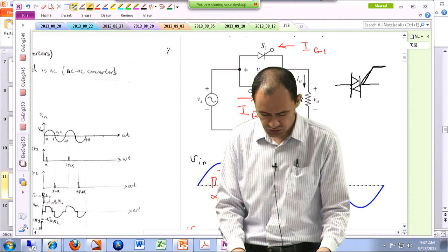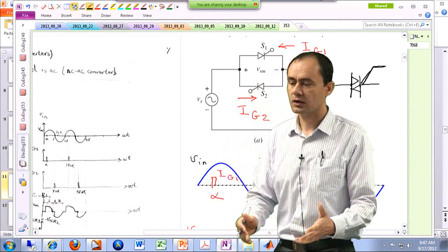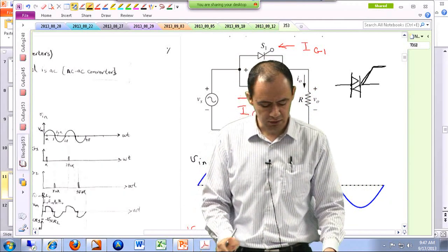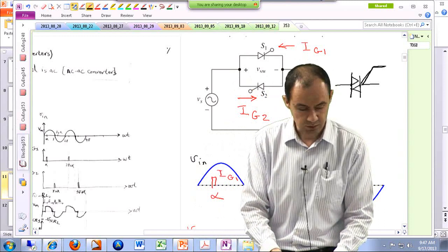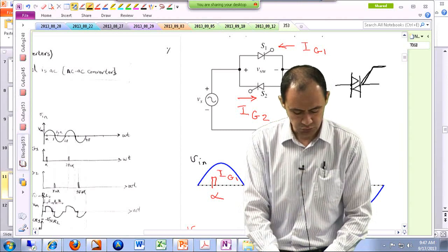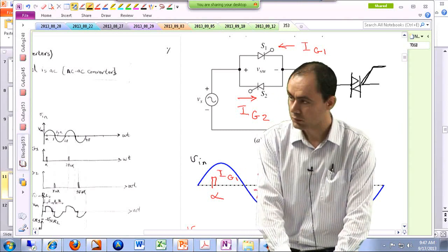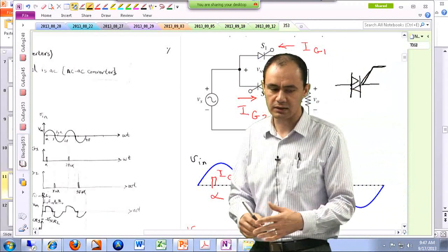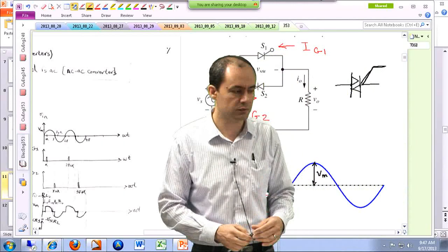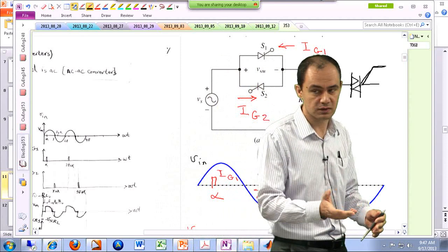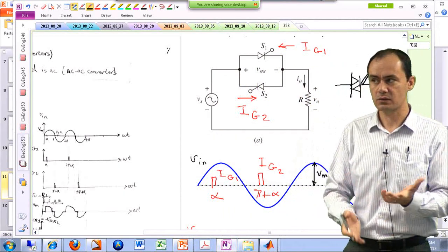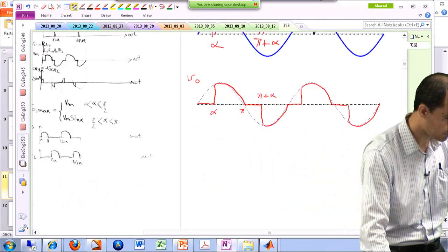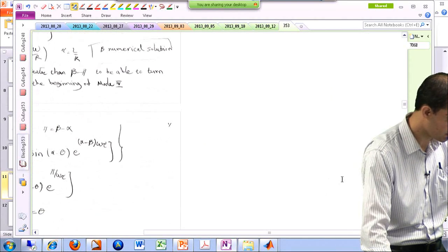So we have talked about the applications of these things. For instance, think about your laptop. Laptop batteries are around 19.5 or 20 volts. But this voltage is too high for the CPU to consume, so you have to step down the voltage from 20 volts to whatever the CPU needs. For instance, very long ago it was 5 volts, then they reduced it to 3.3 volts, then to 2 point some volts, and now it's like 1.7 volts. In the future it's going to 1.3 volts or 0.7 volts or 0.9 volts, things like that. So you see that you want to step down the input voltage, which is a DC voltage, to a lower DC voltage, and the buck converter comes in handy. So let's talk about the buck converter.